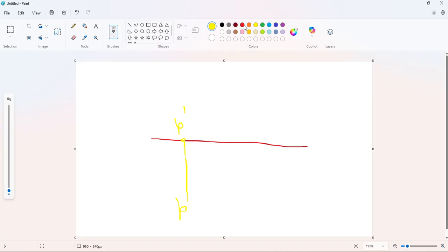So I'm just going to do one thing. The given thing is that P dash and Q dash make a line which is at 30° with the XY line, and we know Q dash is somewhere here. We just draw a line which is at 30° to the XY line.